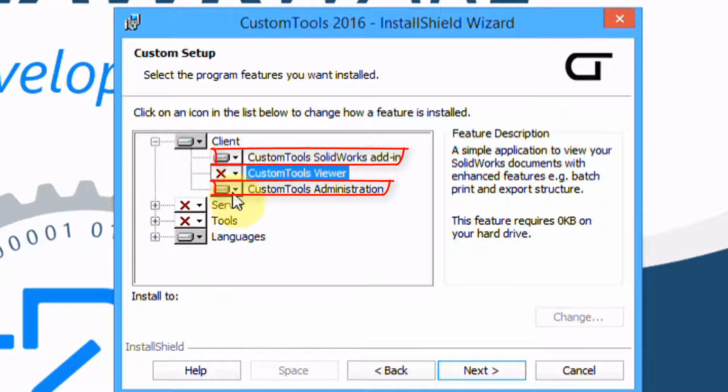Administration, we'll see, we use to set up our database and some users and groups if we want to manage profile access. And inside SOLIDWORKS, we have access to modify the profile itself. And there are options that exist in there that will only show up in there. They won't show up in the profile editor in administration. So we definitely need both.